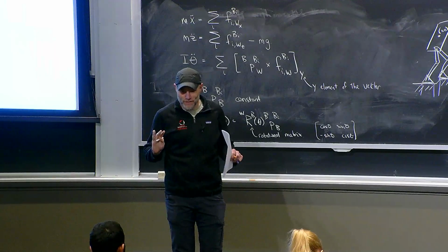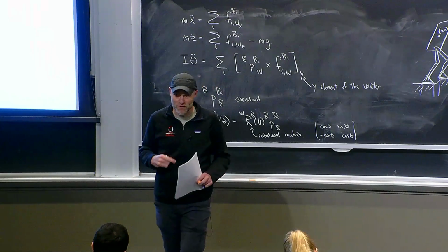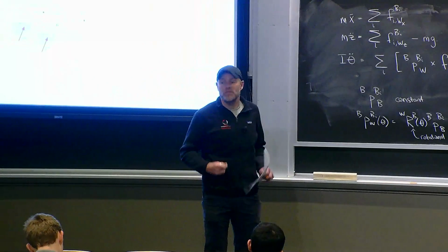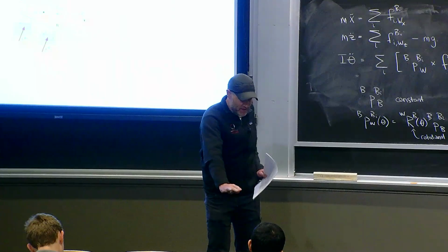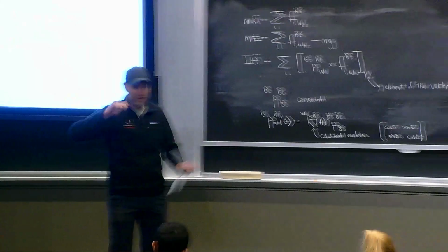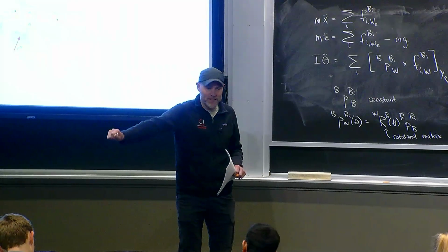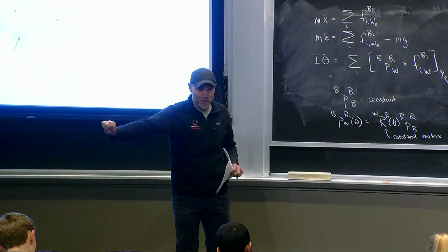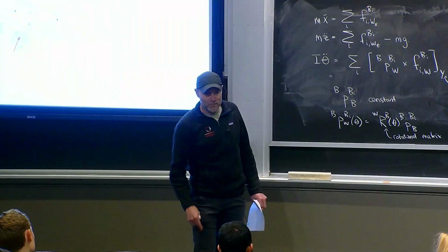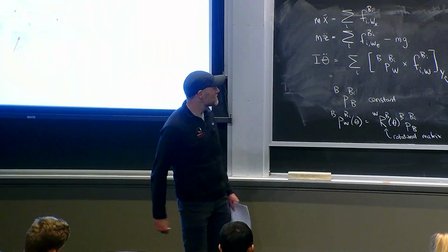Suddenly, you have a center of mass that is going to be moving through space, and maybe tumbling through space if the angular terms matter. The way that you get to move that through space is by making selective contact with the affordances available: the ground, possibly handholds, other things like this. Only when you are in contact do you get to turn on your actuators and apply force, and even then your force is only going to be, typically, if it's a foot, you're pushing down, you have unilateral force. You can't pull on the ground unless you're wearing suction cups, right?